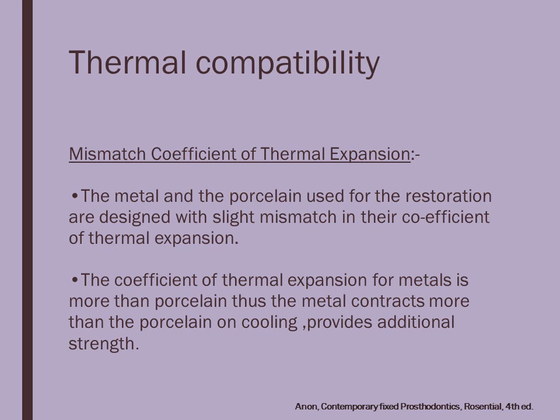So that when the coefficient of thermal expansion is different, and that for metal it is more than porcelain, the metal contracts more than the porcelain, and as a result, because the metal lies below the porcelain, it's the substructure, it contracts more, and it creates again the same residual compressive stresses and provides additional strength.